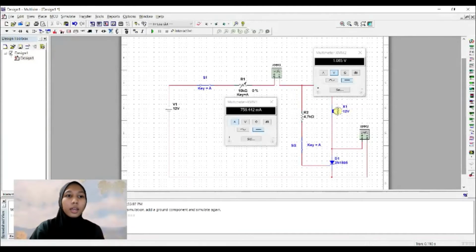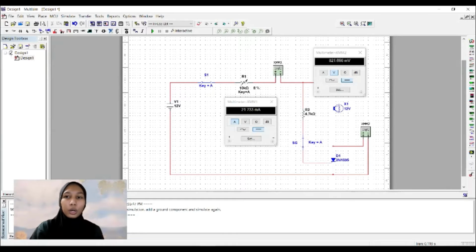And lastly, the value of VR1 is increased slowly while IA is observed as it is reduced to determine the holding current, which is IH, and at some point the SCR will turn off. So the IA is the current indicated just prior to turn off occurring.